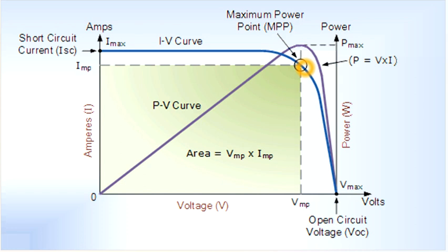See, this is the P maximum point, right? The point at which the power becomes maximum, and the corresponding voltage downwards and the corresponding current on the left side, are nothing but the maximum current and maximum voltage. Remember and understand, they are not equal to the short circuit current and open circuit voltage.